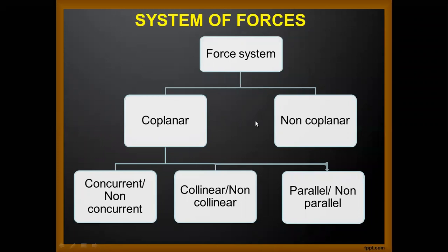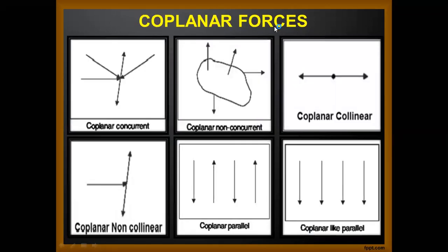I have some examples based on that. Here you see I have shown the coplanar forces. Here you see coplanar concurrent. Concurrent means that the forces are acting at a point, and coplanar means that all the forces are acting in a single plane. So it's called coplanar concurrent forces.